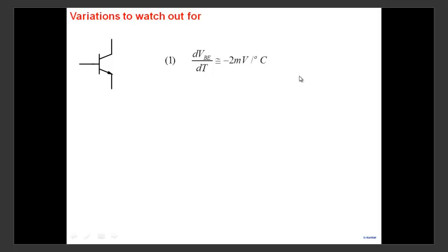All right. And we said that while biasing, because all the amplifier's characteristics depend on the transistor bias current and bias voltage, we have to make the bias stable. And now, when we say stable, what is it? We have to ask ourselves, what is it that is causing the deviation in the bias point? One of them is that with change in temperature, the base emitter voltage deviates from its normal value. Approximate deviation is 2 millivolt per degree Celsius.